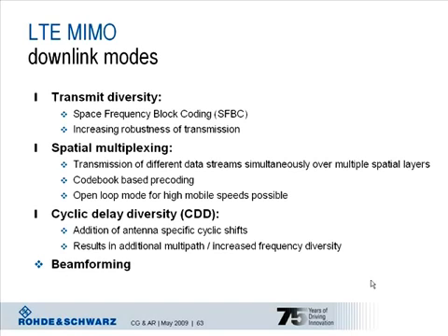It uses a space frequency block coding scheme, SFBC, as an additional antenna coding. As explained on the slide before, the transmit diversity mode increases the robustness of the transmission, but not the data rate. The space frequency block coding scheme will also be further explained in the following to give you an impression of what is really done there with the signal.